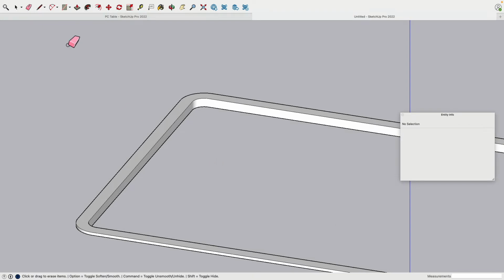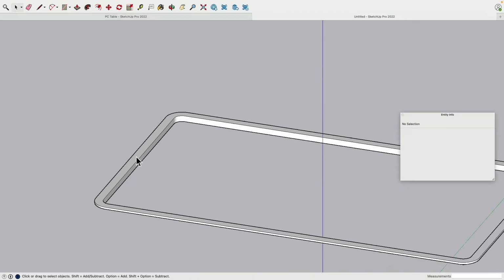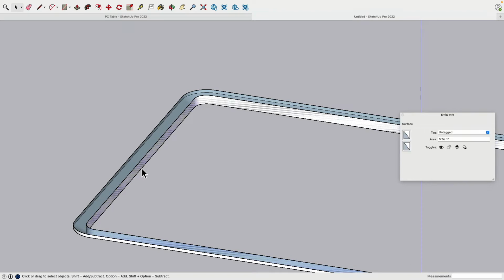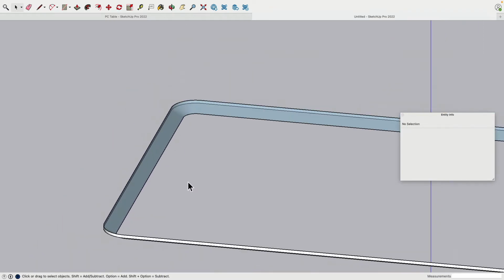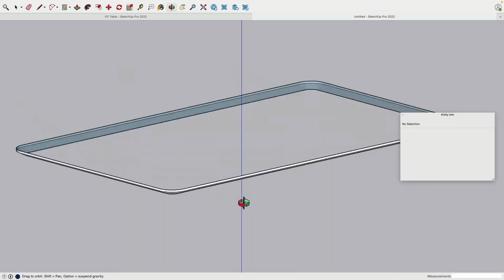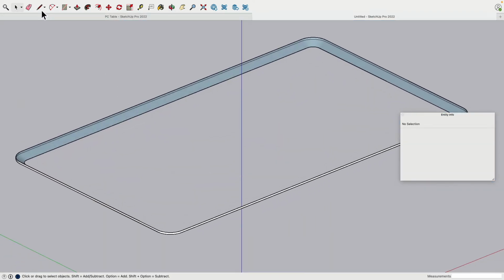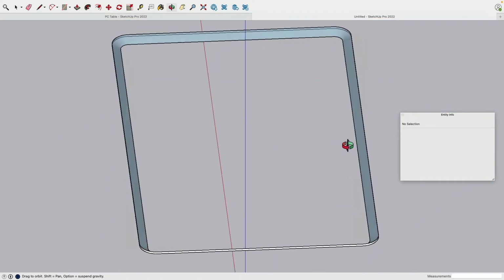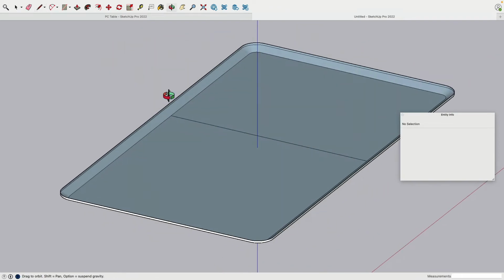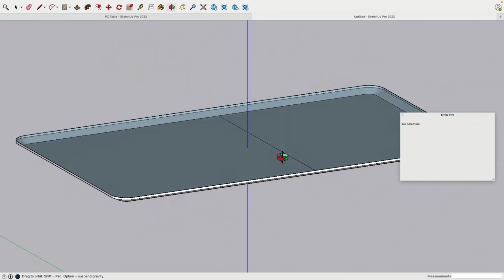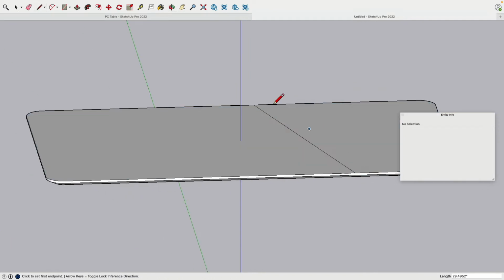Obviously the tabletop is missing, so I will select the top face, select this inner face, delete each, double click on this ring here, the inner loop, delete it. And to fill in the rest, I can simply draw a line between edge to edge at the bottom and also on top. It doesn't really matter where to where.